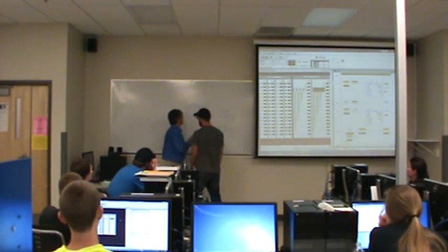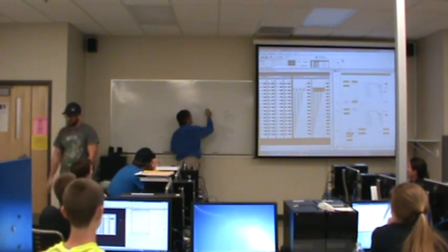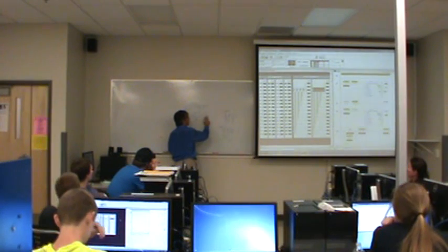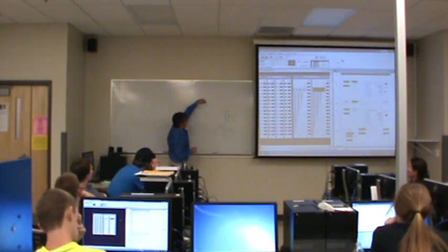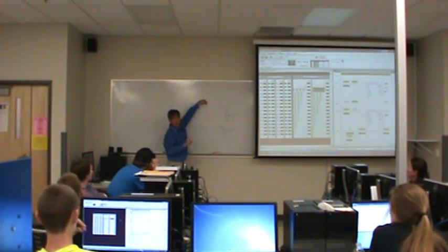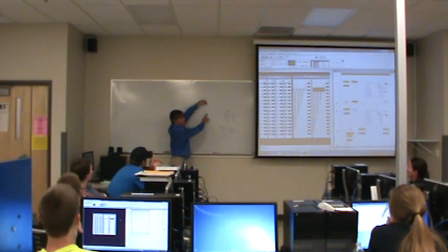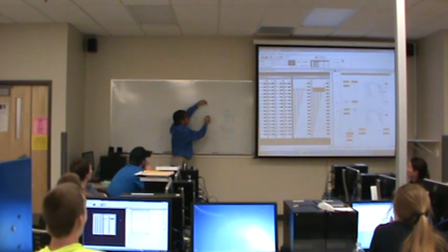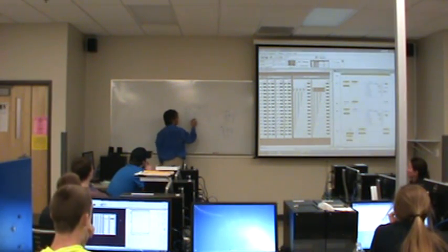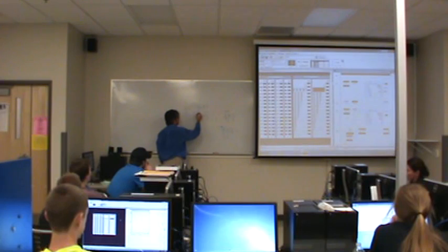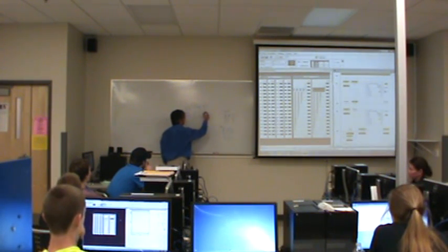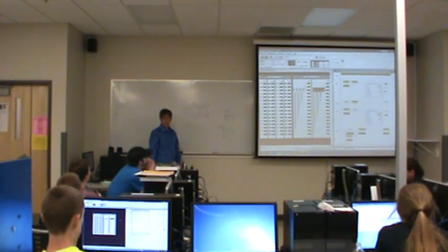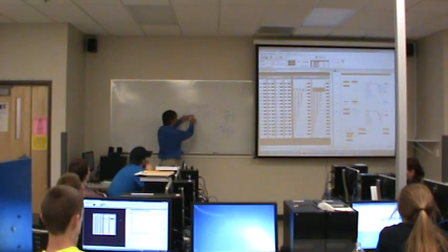Good question. Yes. The question is, if these are both on, would this one be on? Yes, it would. But remember that this bit represents an input I'm not interested in. So I would never put a 1 in the mask. I would put a 0 here and force that to go to 0, because then I always know that this will be a 0, I know that this will be a 0, and I know that these two will be a 0. Does that make sense? I know they will be zeros because, look, I put zeros in the mask, and that will force those to be off.